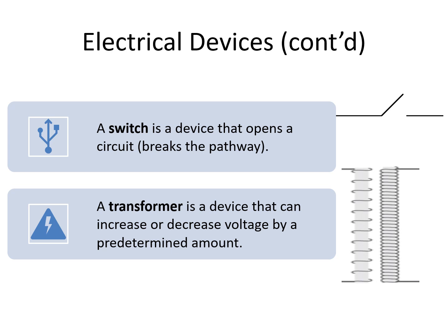And so that's a symbol for the switch up top, and then a transformer. A transformer is actually two independent circuits brought in close proximity to each other. And so what we figured out with transformers is they can transform voltage by making coils of wire around an iron magnet and passing current through the first coil. You'll actually induce a current in the second coil because of the moving magnetic field of the first coil. Now, why does the first coil have a constant moving magnetic field? Well, that's explained by Faraday's law.